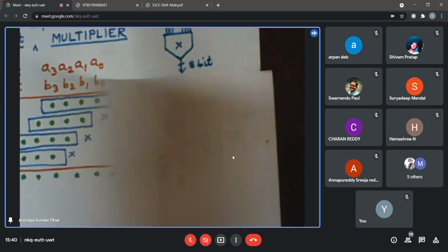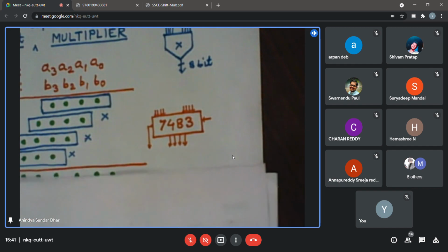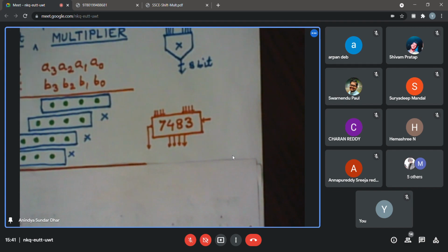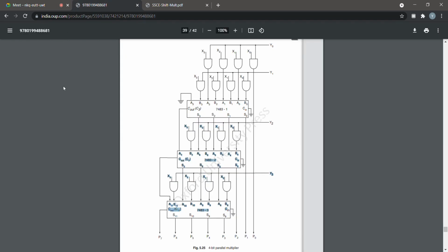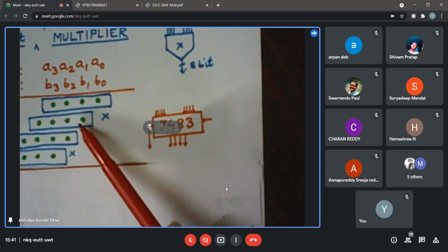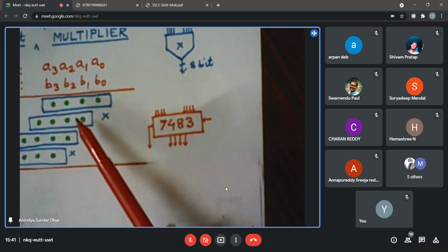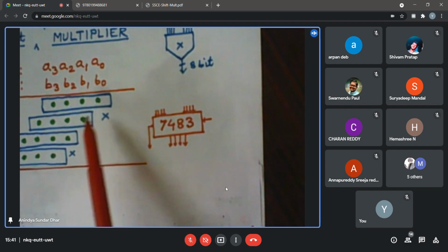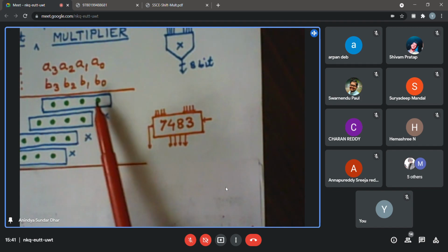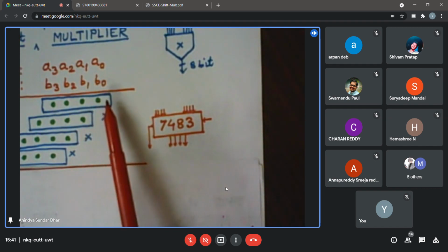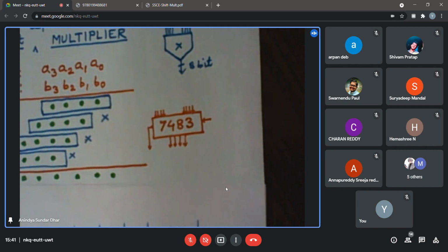Now, how many 4-bit adders are we supposed to use? Initially, if you are having any problem, you may use 2, but certainly I think the intended solution is using 1, because you have seen while analyzing that if steered properly, it may not require more than one 7483. The arithmetic requirement is always for a 4-bit number added to another 4-bit number. Other bits remain constant. But how to handle those bits and keep them in the register, that you can think of. Maybe those bits we want to keep in a register, we can shift, because we do not want to load them. Anyway, I may not give more hint than that.